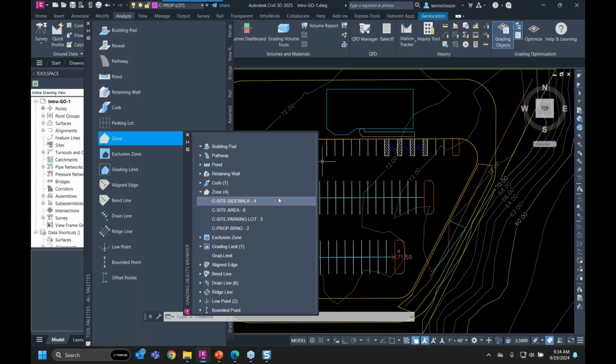On the survey side of things, it might be survey control or calculated points for a design you've done, and you put those into a point group, and immediately underneath that you set the one that says don't show the rest of them, often named something like no display. Same kind of idea, but in this case it's calculating first and going to the next one. It does keep track of them all together, though, because it has to. But nonetheless, it's still saying, let's see if we can achieve this grade first.